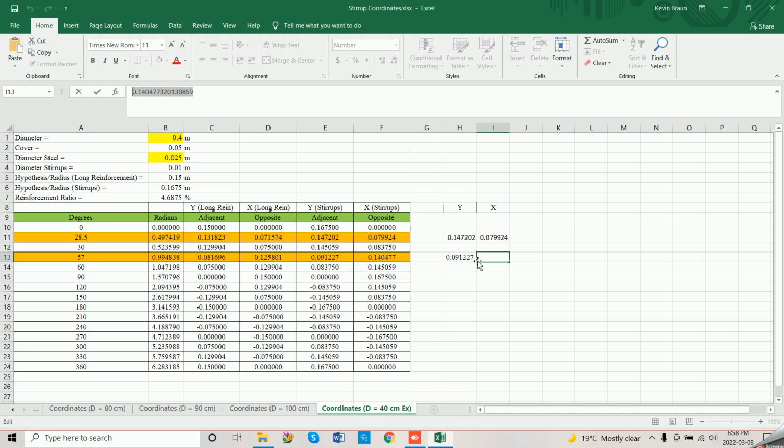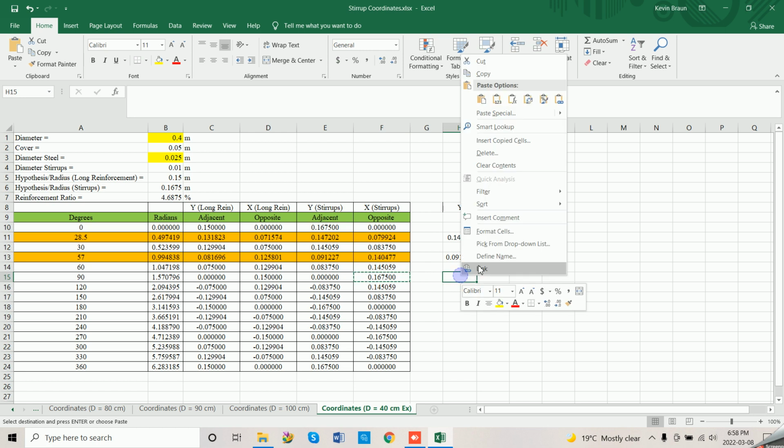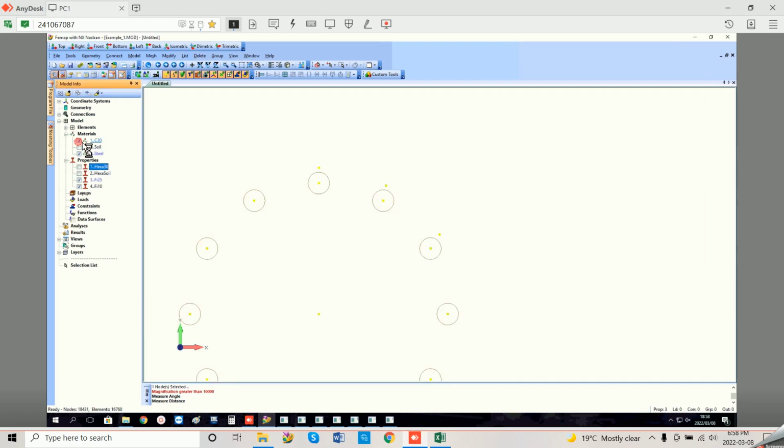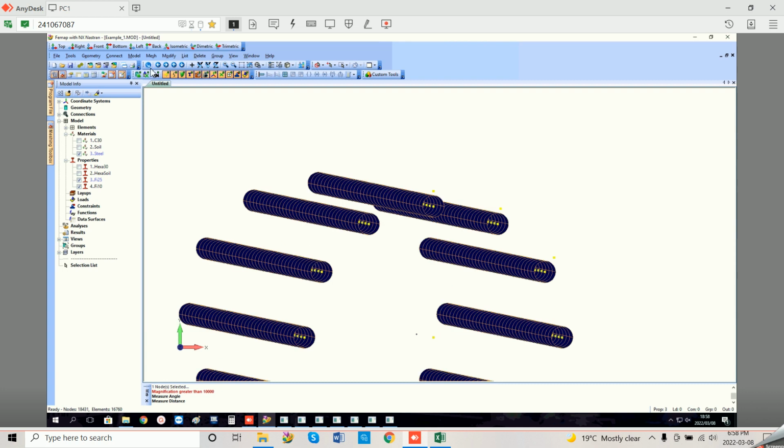So yes, once that's done, then we just do the last one. So the last one is the same coordinate as that, so 0.1675. So we just turn that off, and we go mesh, copy node. So this was positive x, 0.1675.